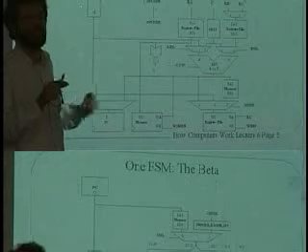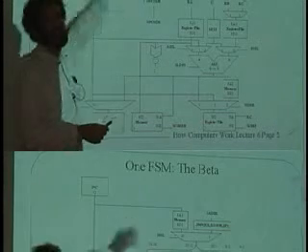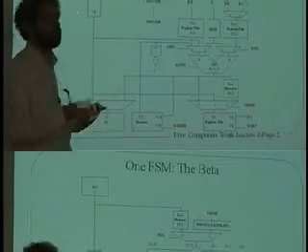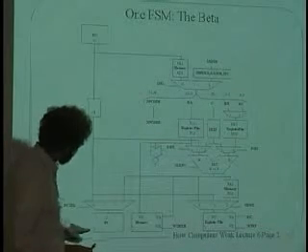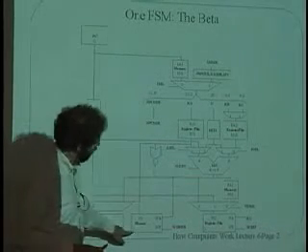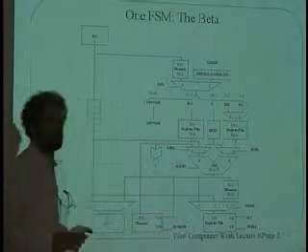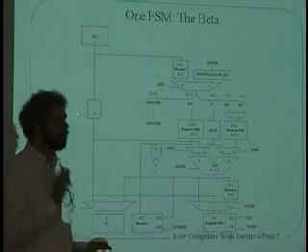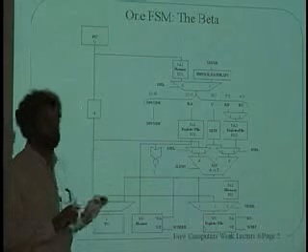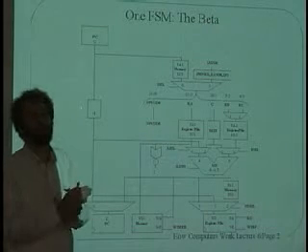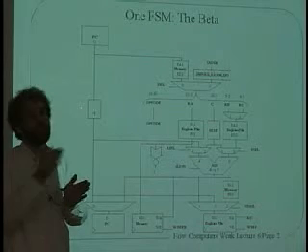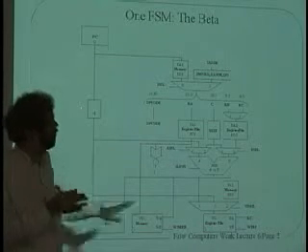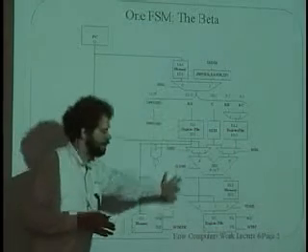And then that will in turn determine what the next state is when the clock goes off. The clock is a wire that connects to all of these little triangles over here, these arrows, and gives the impulse to all these things at exactly the same time, saying, do it now. Okay? And as a result, the machine transits from the current instruction to the next one. And then that instruction does its work here, and all that data percolates through, and then the clock ends.